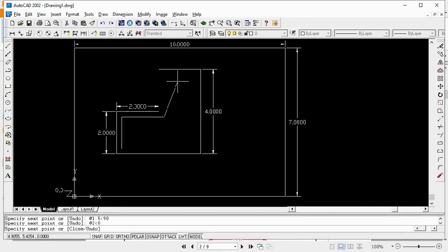Moving up, the same case, what I reduce up here is added down here. So distance remains 2, angle is 90. Moving across, just like here, there is a distance that I reduce from 2 here and another here. So what remains is 1.5. Distance is 1.5, angle is 0. Moving down, what I reduce from 4 here and here totals 0.5. So the distance remaining is 3.5, angle is 270.